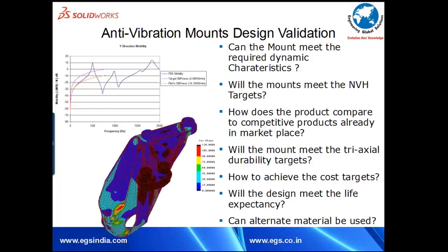Now let us look at the second case where vibration is necessary. There are situations where you need to bring about surface finishes on components, either as a part of the process or because it is being used in the food industry or the medical industry, where the burnishing and the other operations that you do in manufacturing leave post-manufacturing residues sitting on the component.